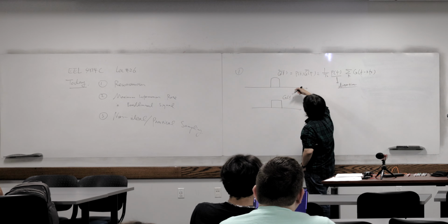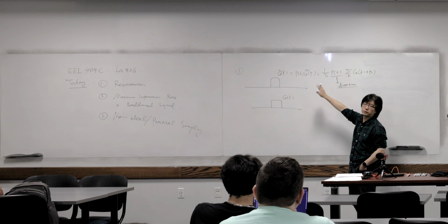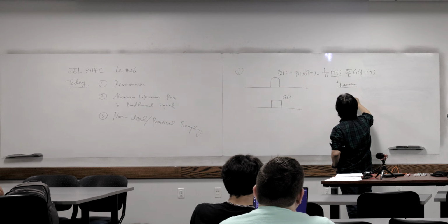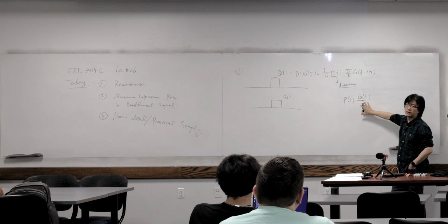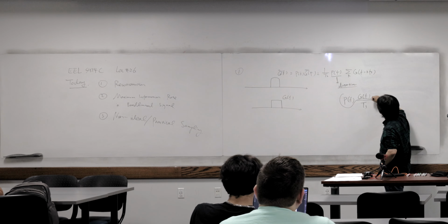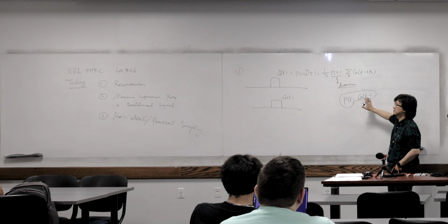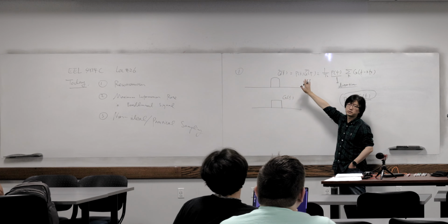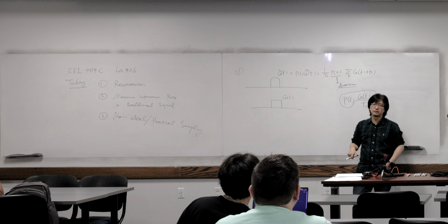In other words, this is kind of a low-pass filter, right? Let's forget about all the high-frequency components. Let's just care about the middle part here, okay? P(f) times G(f) divided by Ts, right? This is what you got for the middle part, and the distortion comes from here. Okay, yeah, we can ignore the Ts, it doesn't matter much. Let's say you have P(f) times G(f) equal to this guy, G tilde(f), and you know G tilde(f). You know P(f). Can you get rid of the impact of P(f)?